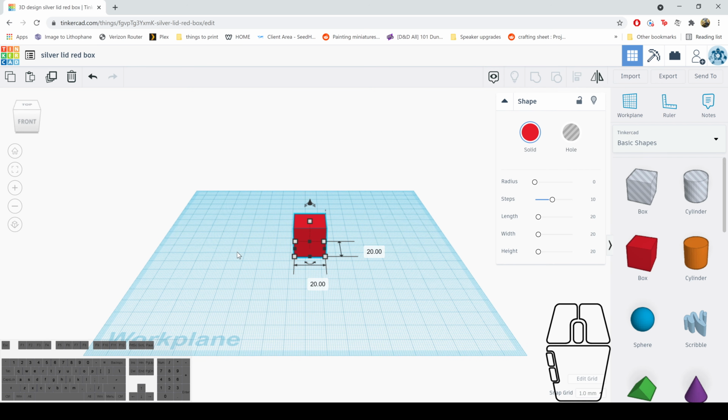And in order to assign the specific dimensions we need, and we're going to be using this tool a lot, is the ruler tool. The button for it is up here on the right. I'm going to be using the shortcut, which is R on the keyboard. So once you hit R or click the button, much like we just did with the box, you're now dragging around a little translucent ruler. Just place it somewhere in front of the box and it'll bring up a whole bunch of numbers.